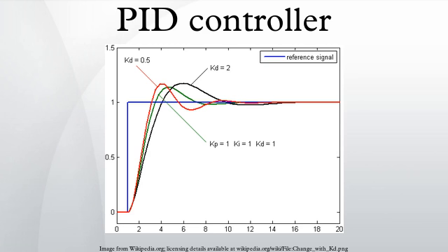process requirements. The response of the controller can be described in terms of the responsiveness of the controller to an error, the degree to which the controller overshoots the set point, and the degree of system oscillation. Note that the use of the PID algorithm for control does not guarantee optimal control of the system or system stability. Some applications may require using only one or two actions to provide the appropriate system control.